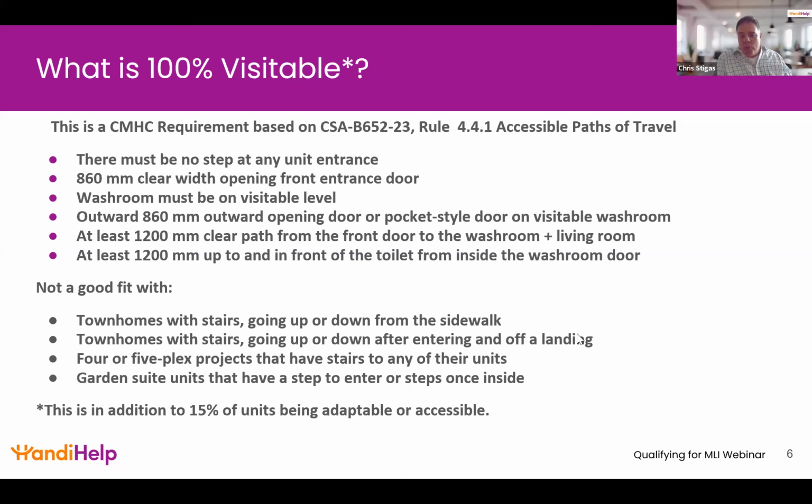we can use the toe clearance underneath the toilet bowl if there's room from the toilet base to the tip of the toilet. If there's some room there, 2 inches, 3 inches, 100 mil, 80 mil, as long as we can document the type of toilet and show shop drawings for that toilet and how much room is available between the base and the tip of the toilet bowl, we can use that to make up the 1200 millimeter.